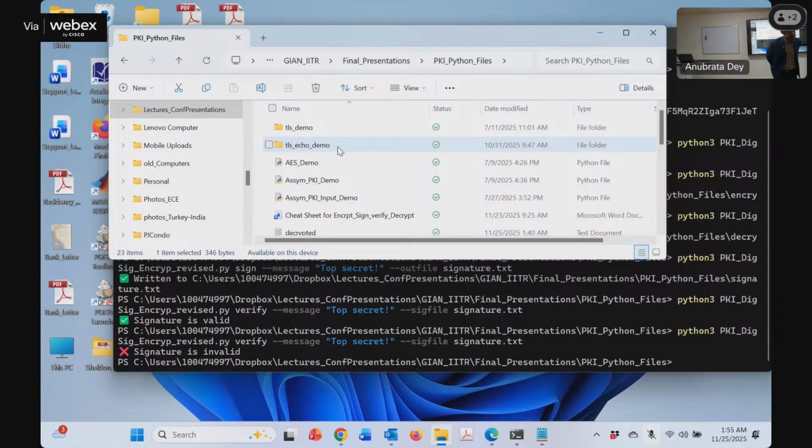For long distances, we are using 104. We are using 104 for remote control center communication. For that, we are using TLS 1.3. Within the substation, we are not using any type of encryption.